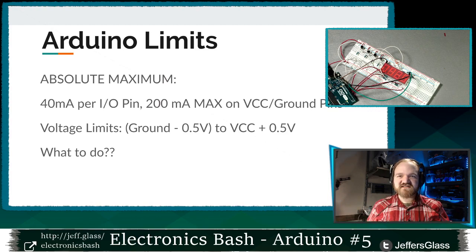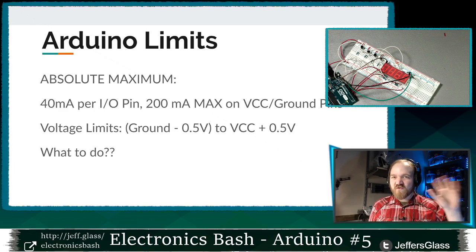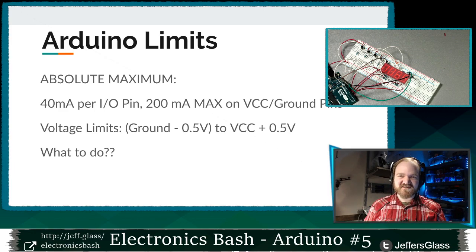So why do we want to talk about transistors and FETs? Well, as we hit on what feels like a million years ago, 4 weeks ago, in our very first Fundamentals of Arduino stream, there are some limits as to the voltage and current that your Arduino can supply. At an absolute maximum, 40 milliamps per pin is what the ATmega chip on the Arduino can provide. We like to keep it below about 20 milliamps a pin just for safety, and regardless, about 200 milliamps max, either in or out of the Arduino, is all you can supply.